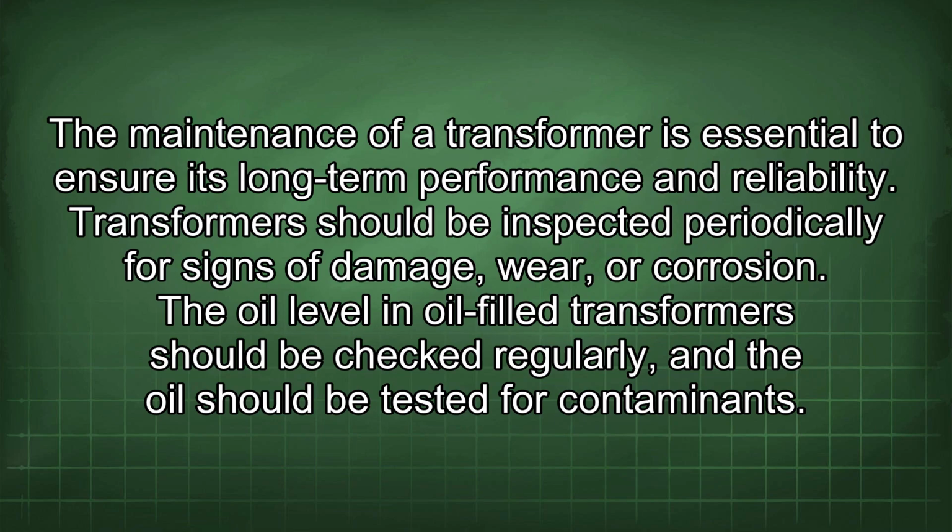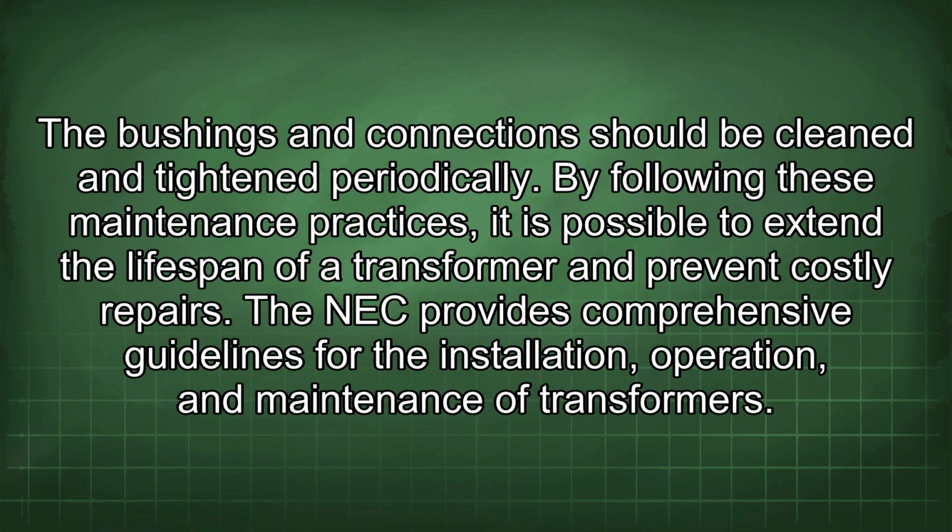The maintenance of a transformer is essential to ensure its long-term performance and reliability. Transformers should be inspected periodically for signs of damage, wear, or corrosion. The oil level in oil-filled transformers should be checked regularly, and the oil should be tested for contaminants. The bushings and connections should be cleaned and tightened periodically. By following these maintenance practices, it is possible to extend the lifespan of a transformer and prevent costly repairs.